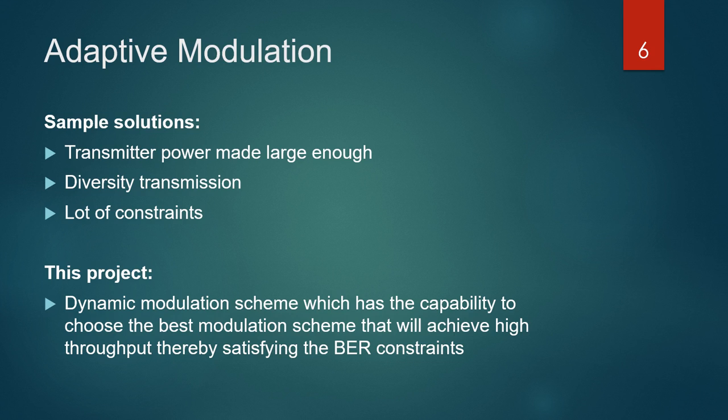The main focus of adaptive modulation techniques is to maintain a constant Eb/N0 value and correspondingly vary the constellation size, modulation and coding schemes, transmitted power, or a combination of these factors. Although these techniques have been found to be very effective and efficient, there are practical constraints to their usage. If the channel is modified at a rate faster than it can be estimated at the transmitter, then adaptive schemes do not perform well. In this presentation, we shall see the analysis of a novel method using a simple algorithm that determines the best modulation scheme that can be used for a flat fading channel where the channel characteristics change for every time slot.